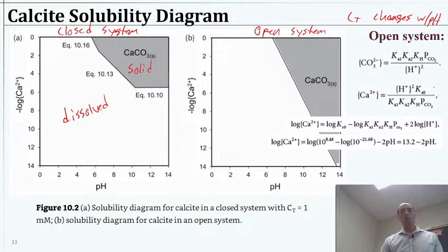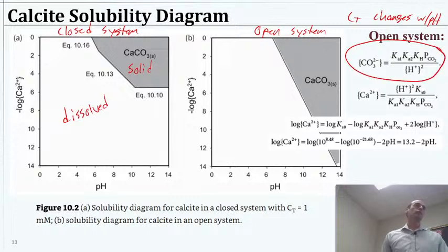So given some partial pressure, also a function of pH, we can then put in this equation and find the carbonate at any pH. There's several constants in here, including the constant for water, and the H plus squared. But really that's pretty straightforward. We can put that in and solve our problem for carbonate.